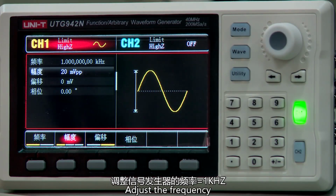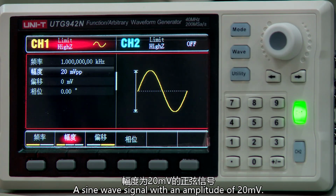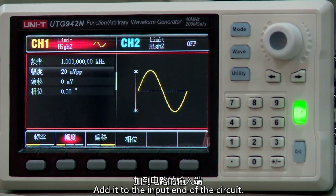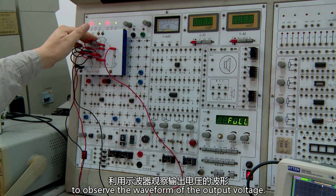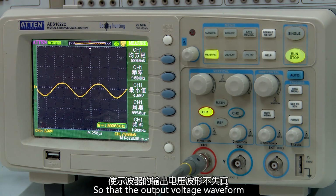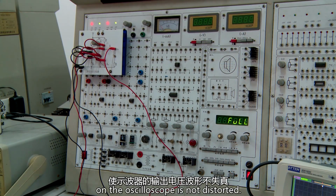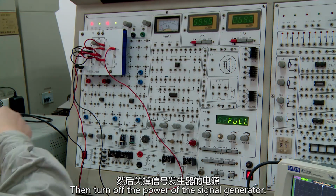Adjust the frequency of the signal generator to 1 kHz, a sine wave signal with an amplitude of 20 mV, and add it to the input end of the circuit. Use the oscilloscope to observe the waveform of the output voltage. Adjust the potentiometer RP so that the output voltage waveform on the oscilloscope is not distorted. Then turn off the power of the signal generator.